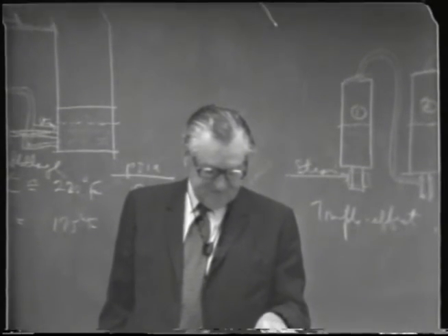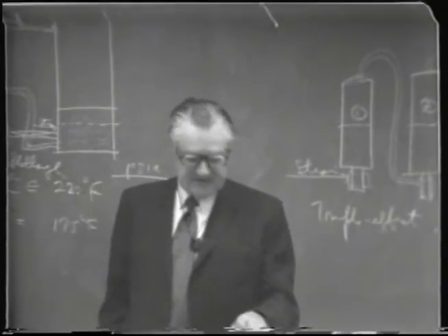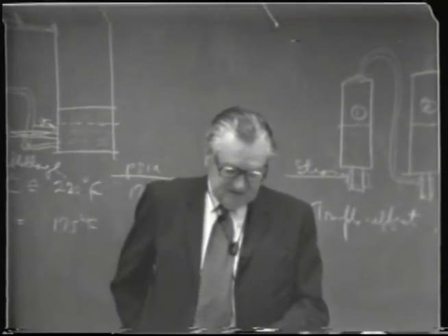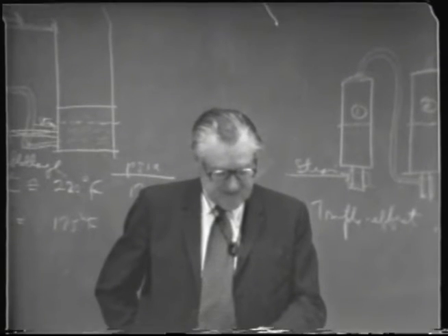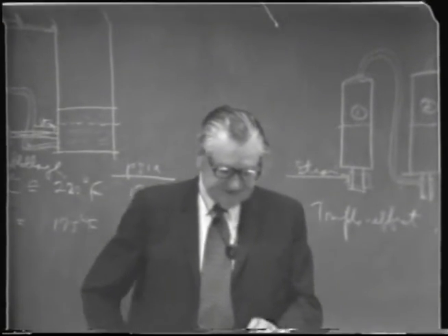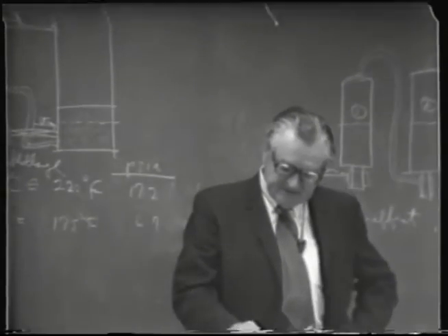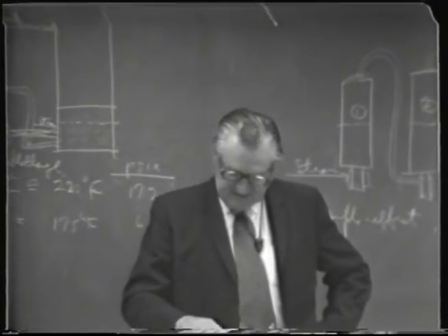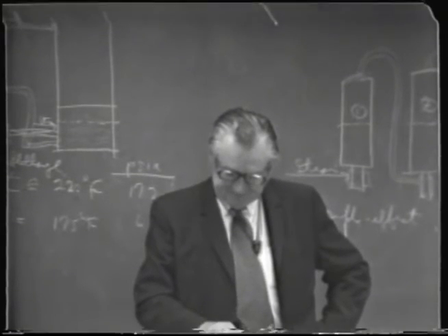From the top of the heads column, of course, the concentrated heads is removed, and the bulk of the alcohol has to be taken off somewhere in that column and returned back into the system. The way I've shown it here, it comes out with the bottoms. Now, it would be possible to draw it off at some other plate level in here and recycle it back into the system. But anyway, open steam can be used in the heads column.